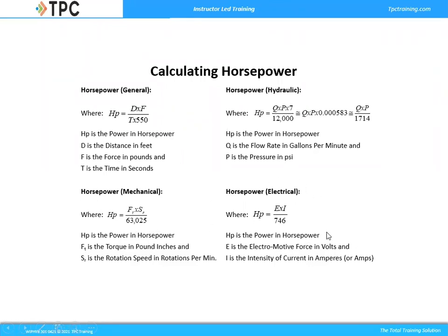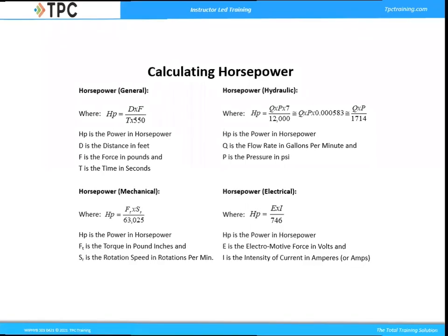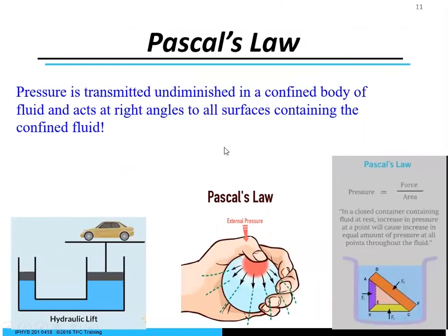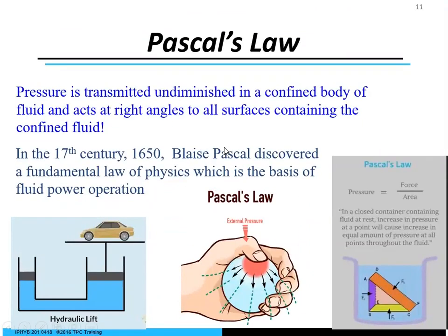They may be different in each one. All depends what the application is. Know your hardware, know your whole application. Go out to the shop and see what is going on out there, right? So Pascal's Law, as I said before, it should be no surprise, is about physics. You need to know a little bit about physics. And so pressure is transmitted undiminished. That's very important. Undiminished in a confined body of fluid and acts at right angles to all surfaces containing the fluid.